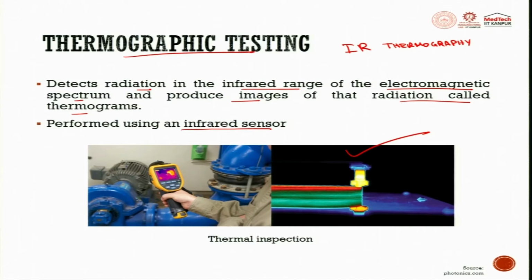So, the accurate infrared testing of the parts should be done in direct line of sight with the camera. So, the camera has to directly focus on where we need to measure the temperature. That means it should not be done with any panel covers or any canopy or any hurdle in between. Otherwise, this will diffuse the heat and the results will not give you the correct readings. So that the thermal imaging can be used to detect corrosion damage, delaminations, voids, inclusions or any other detrimental defects that we have.